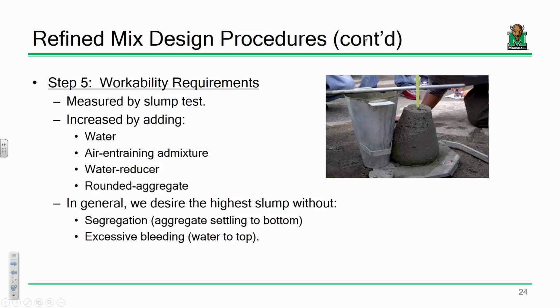But the long and short of a slump test, just so everybody's aware, is you have a very standardized setup. You have a standardized metallic cone. You fill it up in 3 levels, rod it 25 times, and once you lift that cone from the mold, don't turn it, don't twist it, just lift. The concrete that is inside that cone is going to fall a little bit. The more workable your concrete, the more it's going to fall or slump. Okay, so usually what we'll do is we'll turn the cone upside down, set the tamping rod on the top, and just measure that accordingly.